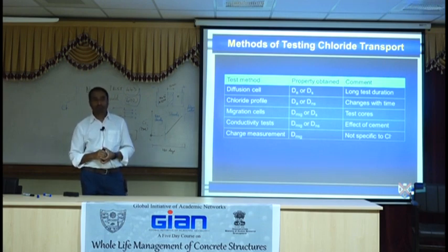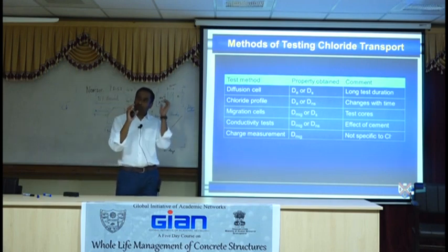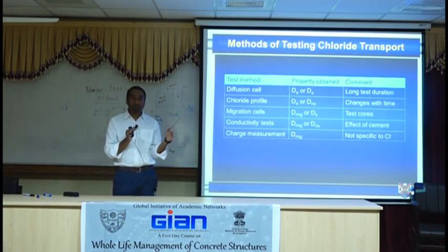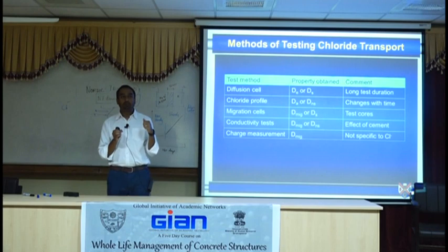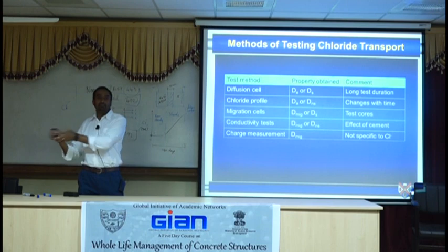Highly likely. So bottom line, you cannot use strength as a performance criteria for durability. Strength is a performance criteria for structural properties. And what we're saying is you need another performance criteria for durability based on your exposure. Chlorides are not the performance criteria if your exposure is carbonates or sulfates. You need a related exposure criteria.